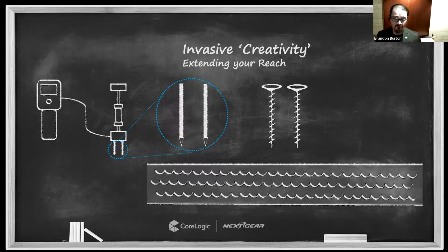In many cases, I have actually used 8, 9, and 10-inch drill bits in order to get much deeper into structural assemblies, so I can range deeper into those materials and then use those left in place as opposed to the wood screws, just to give me that longer range depth, especially when you're dealing with a lot of very thick dimensional lumber. Okay, it can be very, very difficult. Even with a wood screw, it can be very difficult to reach 40% depth in some of those materials.